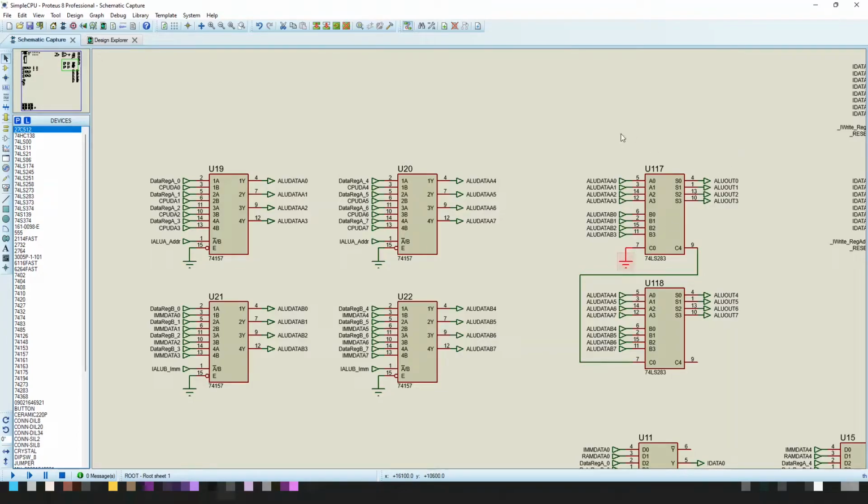Now these adders are 2's complement adders, so if we present a negative 2's complement value here or here, then it will just do a subtract rather than add. Hence the magic of 2's complement binary arithmetic, which is brilliant.